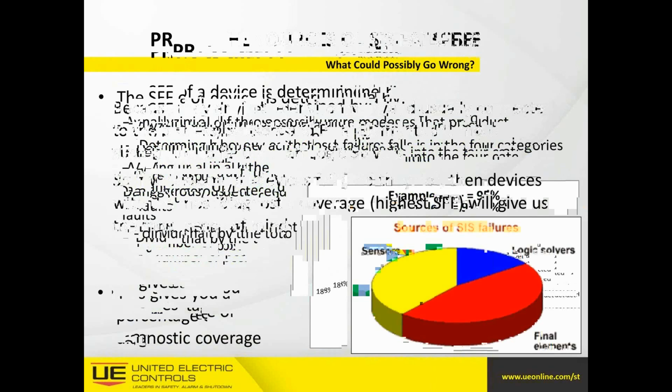However, Michael, as you stated, the numbers are very specific in these documents, and they have failure rates that cover all of the dangerous detected, dangerous undetected, safe detected and safe undetected categories. They all come out as failures in time. These failure in time numbers are calculated out in billions of hours, and it's important to have that supporting document and not listen to somebody like me that just stepped on my knuckles and said rated, because it's very true. Do you have an example of an Exida certification at some point in the presentation? Because it may clear it up.